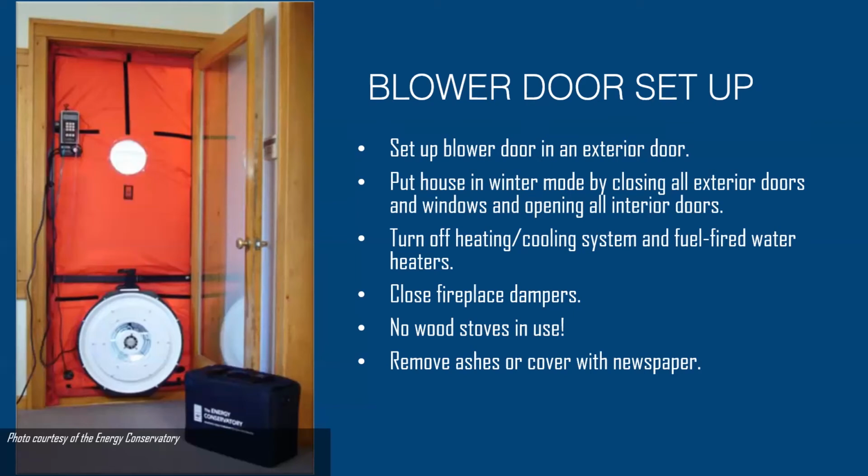Close the fireplace dampers. Definitely don't want to have any wood stoves in use. And it's good practice to check for ashes at the bottom of a fireplace. Either remove them or cover them with a newspaper. You could get a lot of wind coming down that chimney. If it's a pile of ashes, they might just end up in the living room.